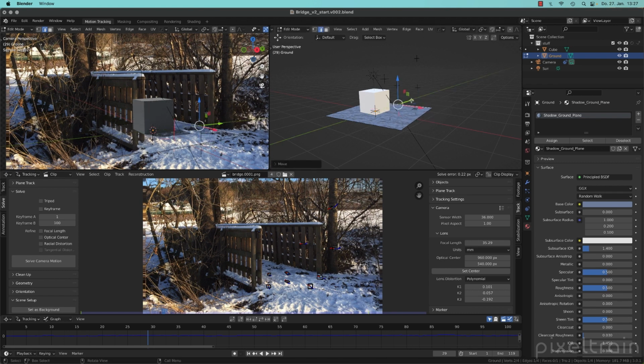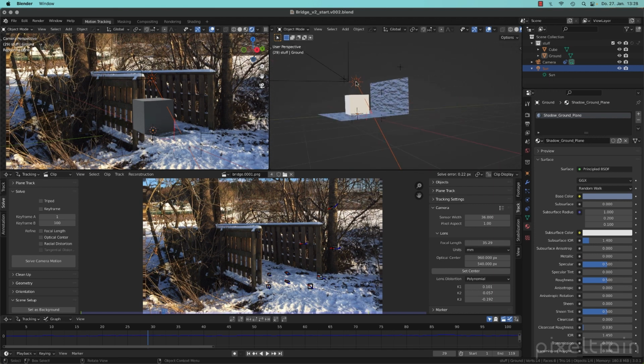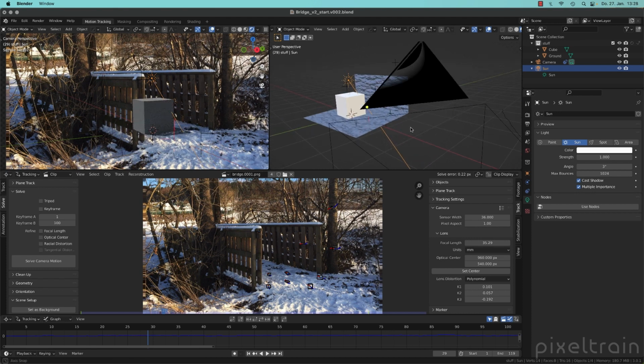So what I really often do with Shadowcatchers is I block out objects in my scene. You can also capture shadows which are going, for example, in this area here. So if the sun comes from this side, you can extrude that, bring it up, and then if you go later to our sun and change the direction of our sun again, you will see that the shadows also crawl over the fence and so on. That's the idea of helper objects. Okay, I think I explained a lot about the Shadowcatcher.